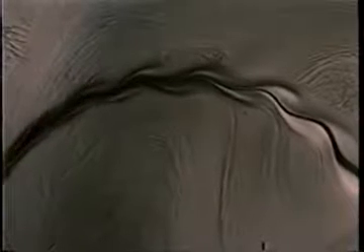A familiar example of flow instability is the flow around the cylinder. When the cylinder is moving through the fluid at less than critical Reynolds number, the flow around the cylinder is steady, although we can see a slight instability in the wake. Increasing the Reynolds number by increasing the velocity, the flow around the cylinder becomes unsteady. A vortex wake develops, the Kármán vortex street. Just below critical Reynolds number, the stability is precarious. A small accidental disturbance is enough to trigger large fluctuations.